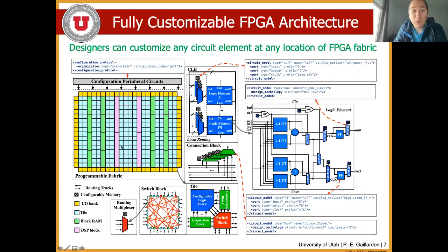So you are creating a SAT problem that is extremely large because you need to evaluate all corner cases and everything. So it just scales in an exponential way with the size of your fabric. So you very, very quickly reach the limits of what your formal verification engine can do. Does that make sense?